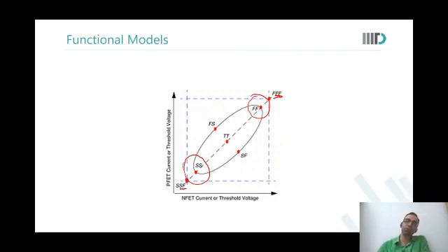When you are verifying small circuits, you may want to verify them over these points also. You do not characterize them, because in characterization a small circuit is usually not an end in itself. You would have many circuits cascaded one after another, and the overall delays would never be at FFF or SSF. But when you're just verifying your circuits, you may want to verify them at these functional points also. Not all foundries provide it, but quite a few foundries do provide these functional models.